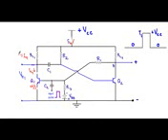That's why, as there is no voltage drop from this point to this point, you'll see that this VCC will appear across this collector to emitter terminal of the transistor Q1. That means initially this VCC will be the stable state of the transistor Q1, or the output of the transistor Q1 will be stable at logic 1.